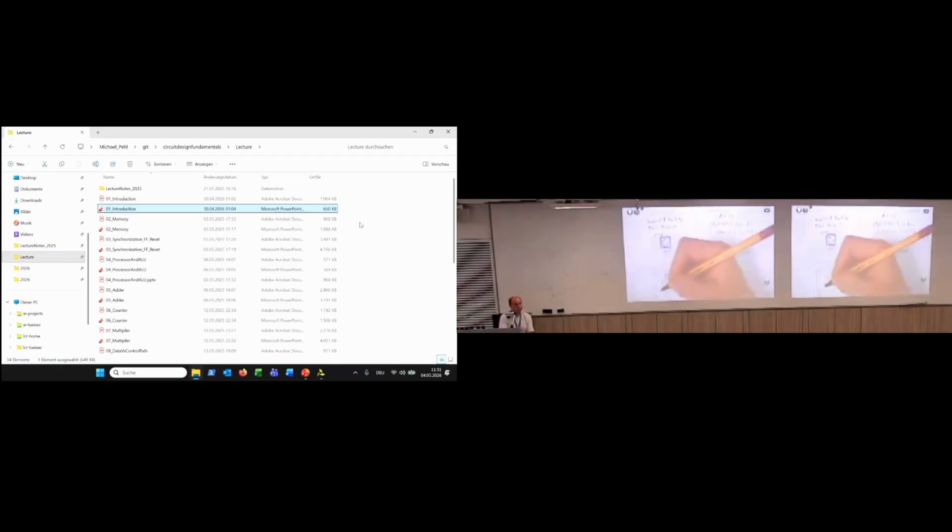And for the fab, we do not have to separate this, because if it's under the gate, then anyhow it is not manufactured. So we can just draw one stripe here, and oops, it should be stripe here, but I did a minor mistake, which I can still correct, because I need a second one, which is N diffusion, and the N diffusion should go here, and the P diffusion should go here. So what do we have by now?